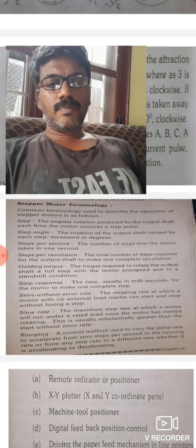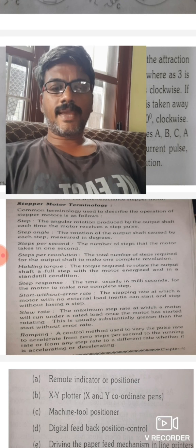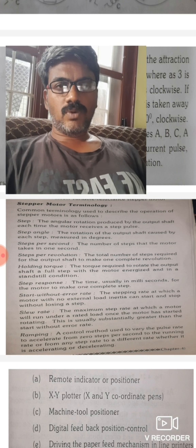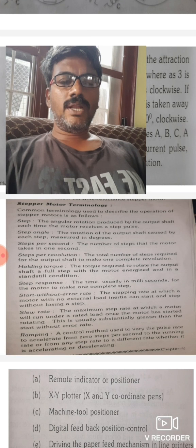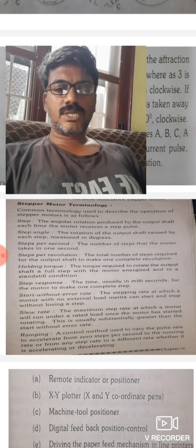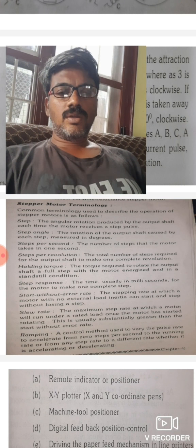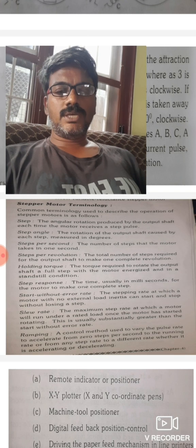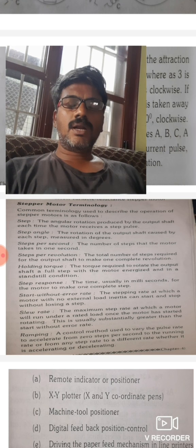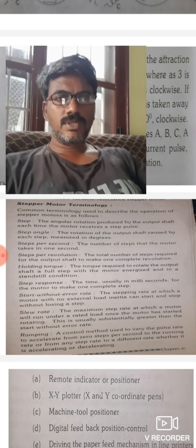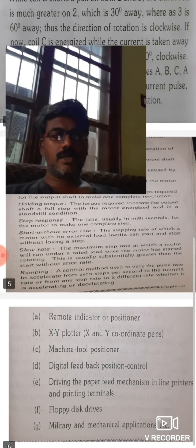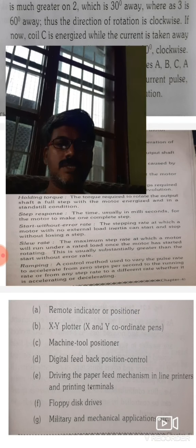The motor can position an object accurately on an input command in the form of a number of pulses, provided it is used in the response range. Simplicity and economy are advantages of this motor, together with the fact that it is a digital device and compatible with computer outputs. So the following are some important applications of the stepper motor.